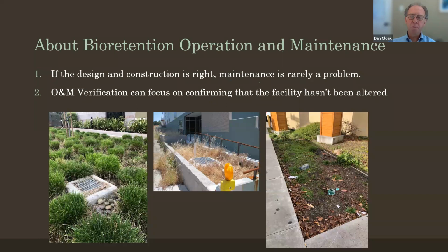The maintenance must be ensured by the property owner going out there and doing something with it regularly after storms. We need O&M manuals, we need O&M requirements, we need matrices, we need an inspection program to make sure that municipalities go out there and check on a regular basis that these are being maintained.